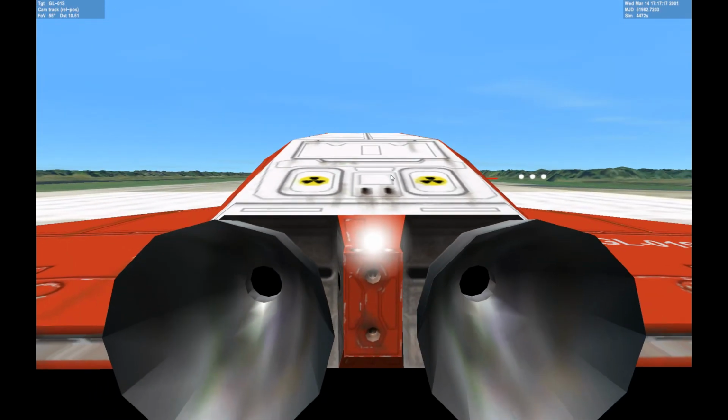So what happens is you turn your engines on, and the atmospheric pressure is actually higher than the pressure in your fuel chamber, and so you turn that valve on, and the flow goes back up into the tanks, which isn't good. So basically, yeah, no combustion happens, and you're stuck. So you have to be careful about that.